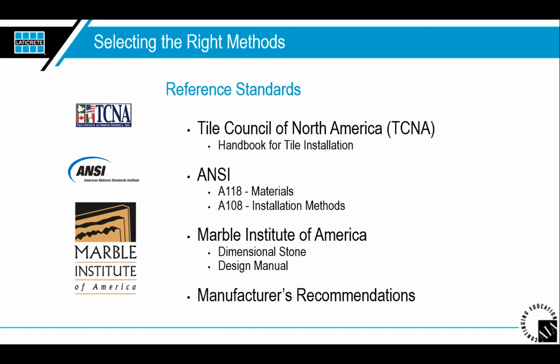And then when it comes down to it, you actually have the manufacturer's recommendations, which is again for the tile or for the setting materials. For example, the manufacturer of the tile installation materials provides product information and installation instructions. Maybe they need a specific type of thin set that's going to be used to set their glass, for example. They will also offer things like material safety data sheets, also known as the MSDS sheets as well.